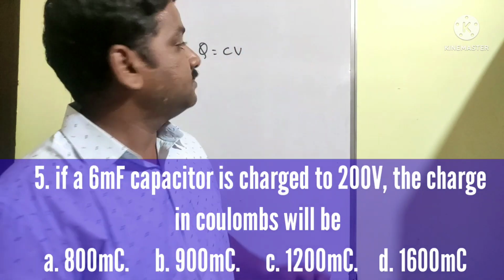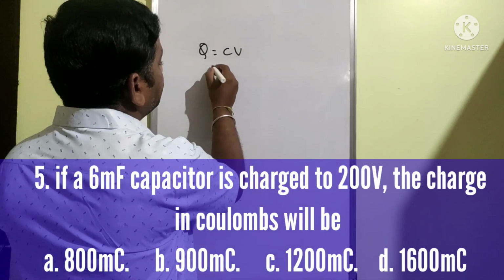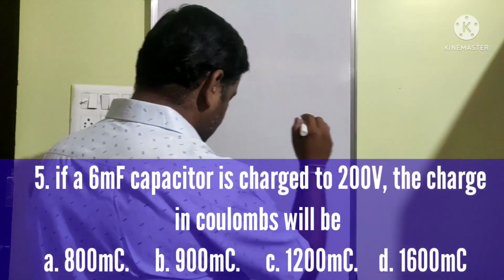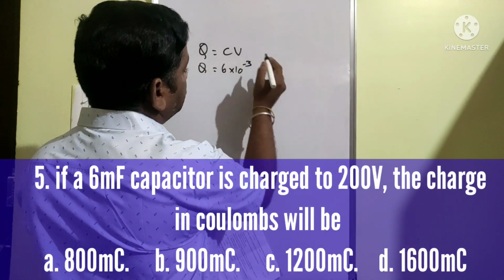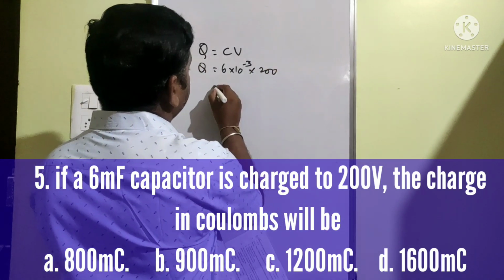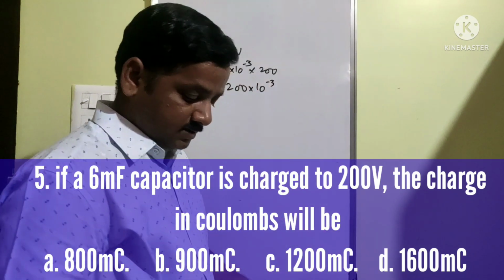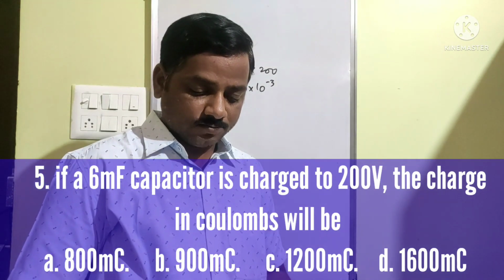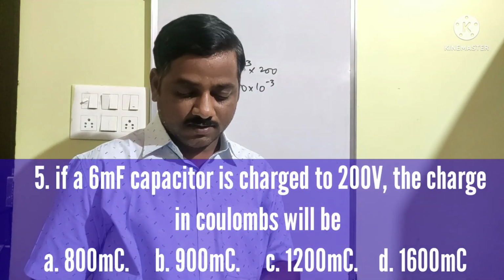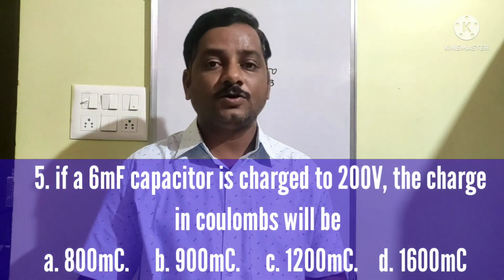If we increase the voltage, the charge will increase. That's the point. In this Q is equal to CV, we need to find Q. They have given the values, just substitute them and get the answer. So 6 into 10 to the power of minus 3, because it is 6 millifarad, into voltage of 200. 6 into 2 is 12, so 1200 into 10 to the power of minus 3. In the options, you can go for 1200 into 10 to the power of minus 3 coulombs, or you can say 1200 millicoulomb.